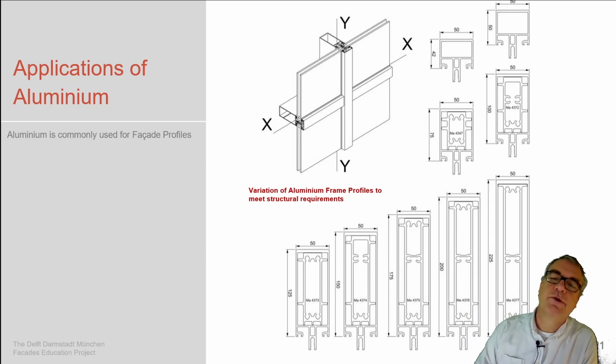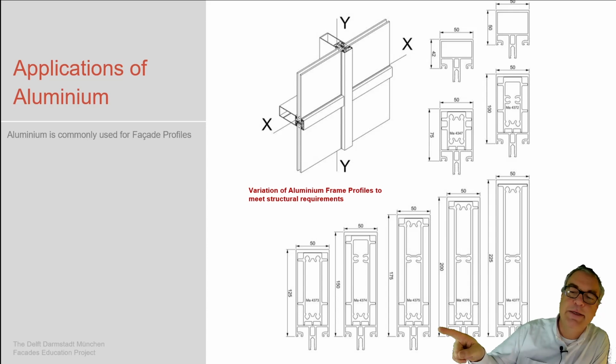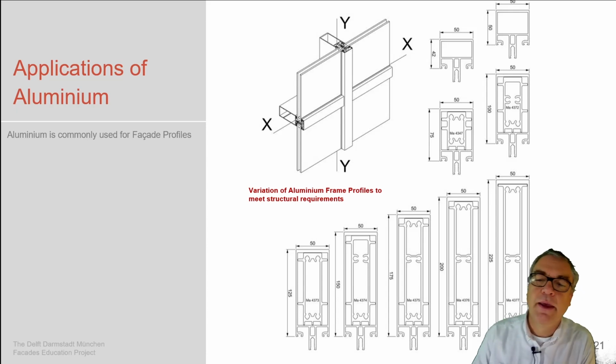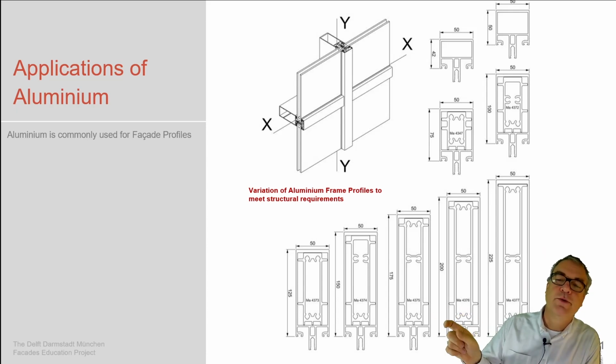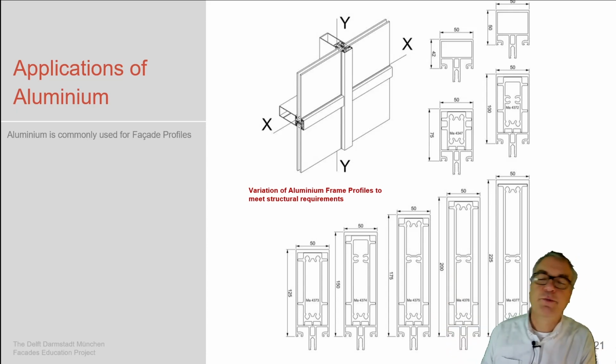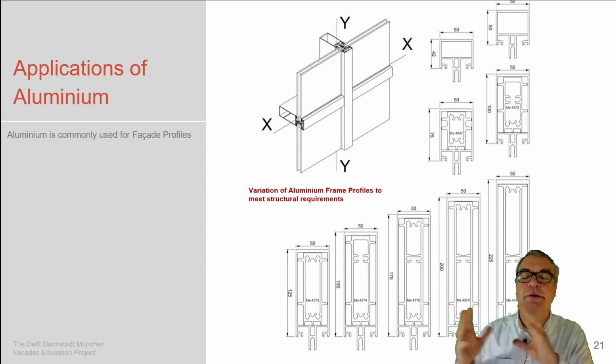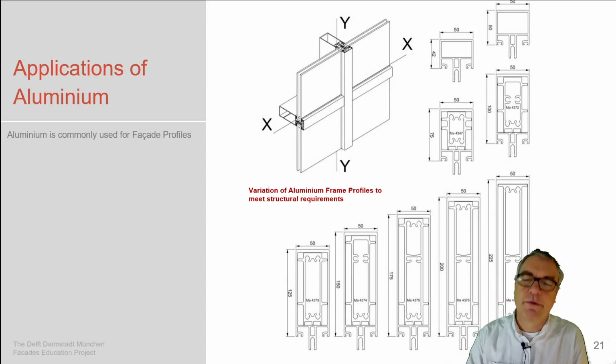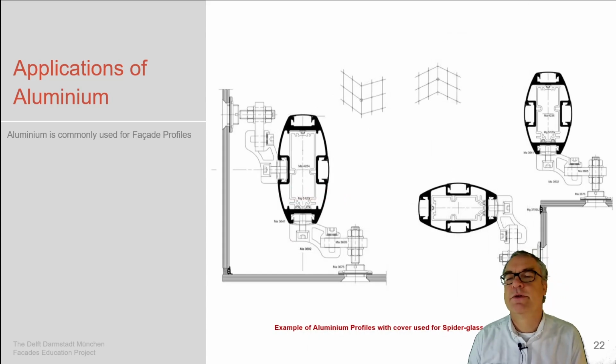There are several which have all the different profiles, and what we nicely see is they have all these sharp edges with the screw channel and the channels to take the rubbers for the sealant, and some additional screws to be brought in. Also, additional strength is brought into position to make the profiles, if they are larger and deeper, capable for the structural loads being used. You can imagine each of these profiles needs an individual die, with obviously the costs related to the die. A different setup, a different functionality.